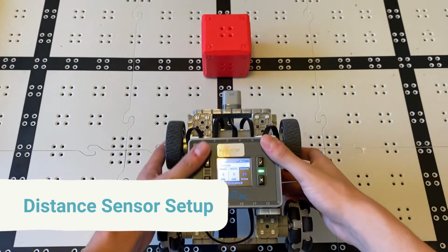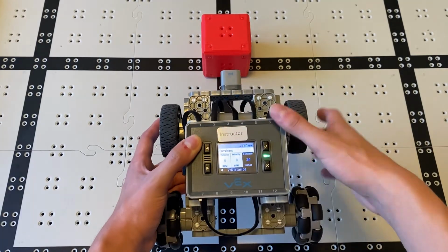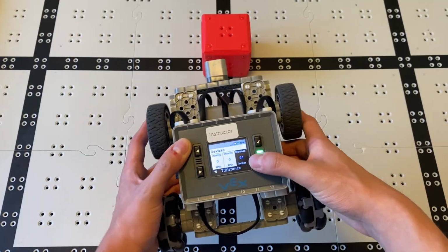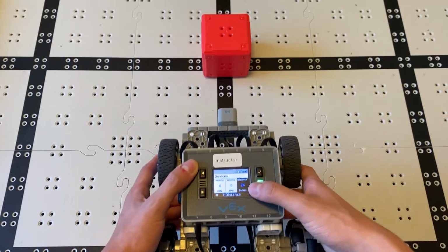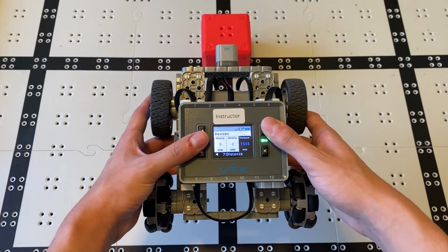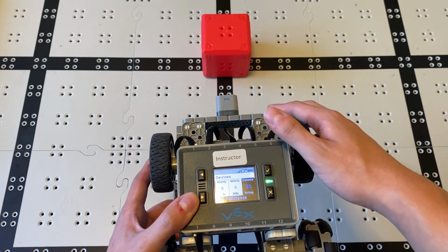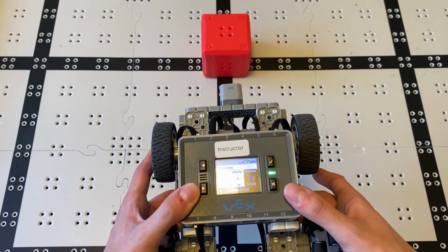Alright, so I've got my base spot here with a distance sensor attached on the front and plugged into port 7. From the devices menu, we can see different readings from the sensor, and like the name suggests, it measures distance to an object, and we can see that printed on the screen in either inches or millimeters. The sensor can also detect things like the approximate size of an object, along with its approach speed.